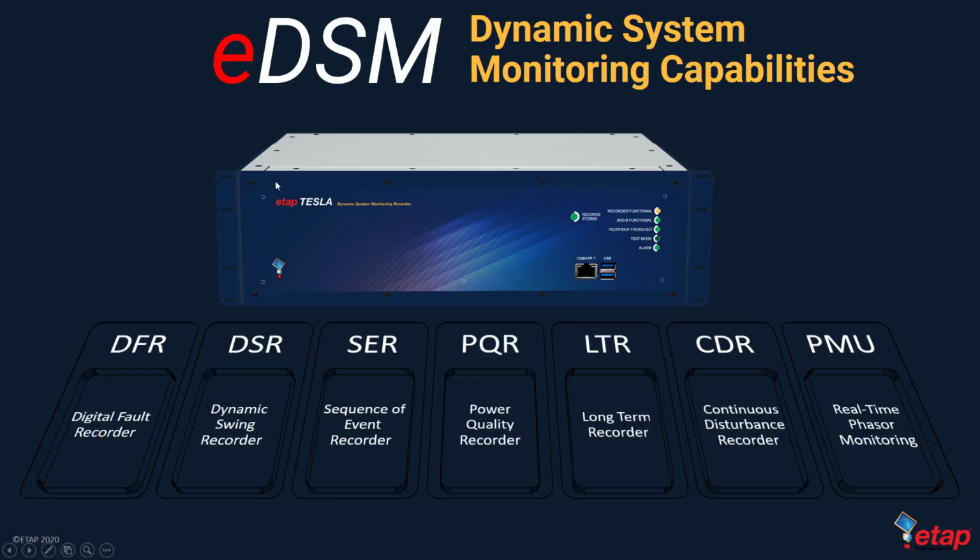So therefore, for this purpose, we use this dynamic system monitoring recorder that essentially acts as a digital fault recorder, a dynamic swing recorder, sequence of event recorder, power quality recorder, a long-term recorder, continuous disturbance recorder, as well as has PMU or real-time phasor monitoring capability.